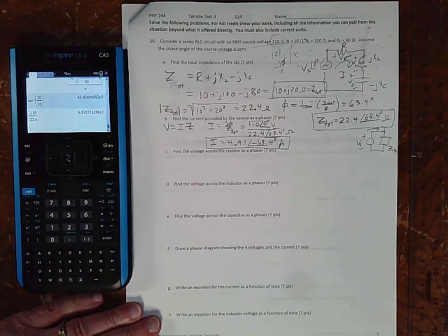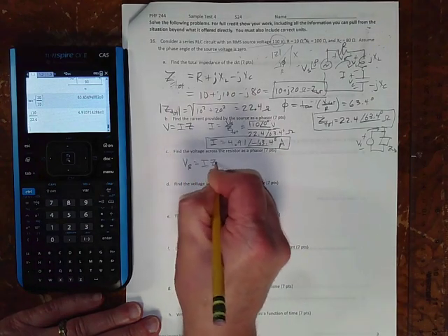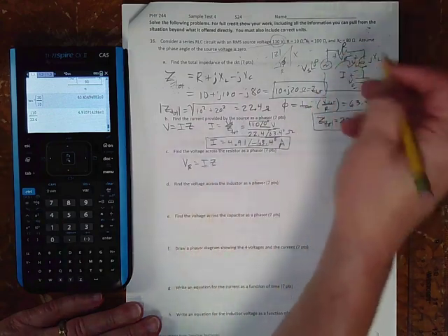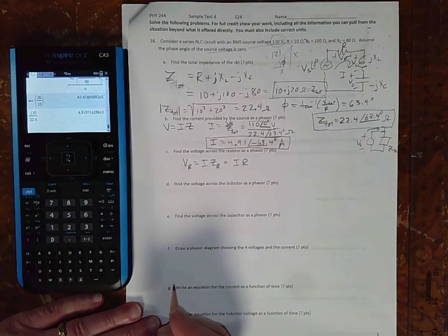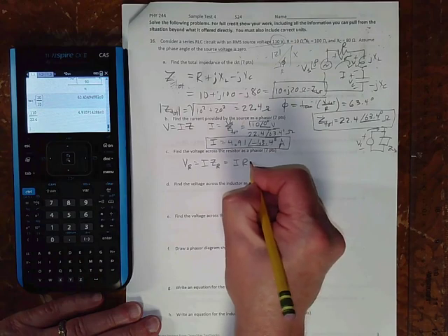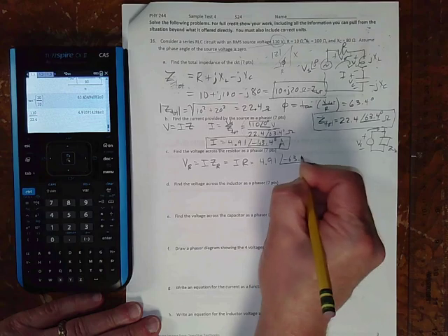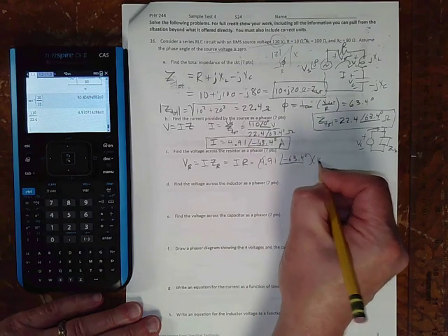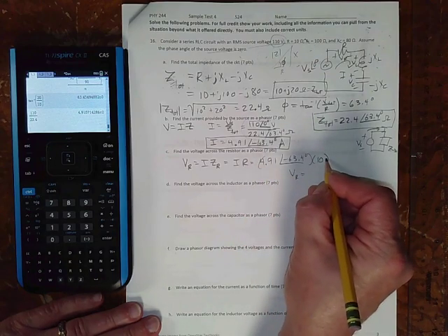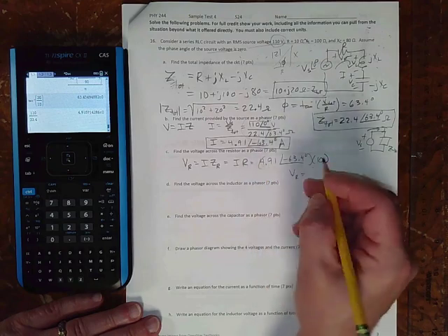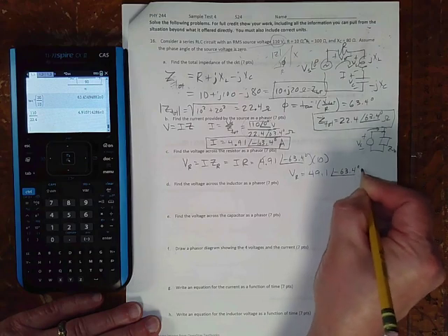Find the voltage across the resistor as a phasor. So V sub R: again, V equals IZ, Ohm's law still works, and there's only one current, but we want Z of the resistor, which is just back to our old V equals IR version. But now I is a complex number, 4.91 at an angle of negative 63.4 degrees, and R is 10, or 10 at angle 0 if you want to think of it that way. Basically, you just multiply magnitudes, and so we get 49.1 at an angle of negative 63.4 degrees volts.